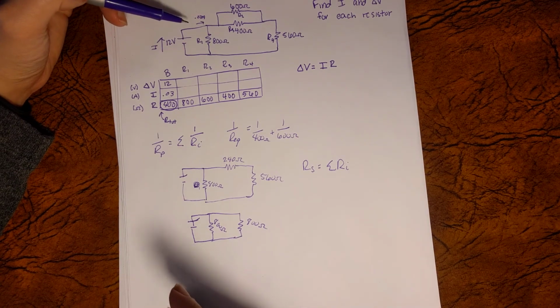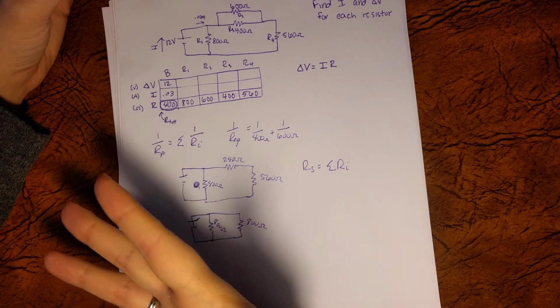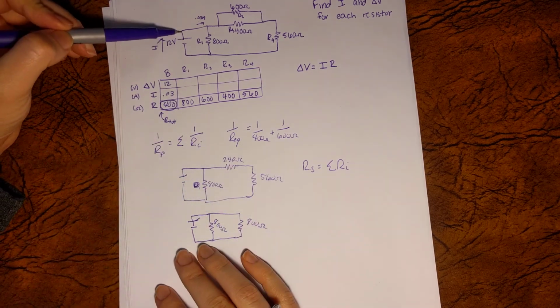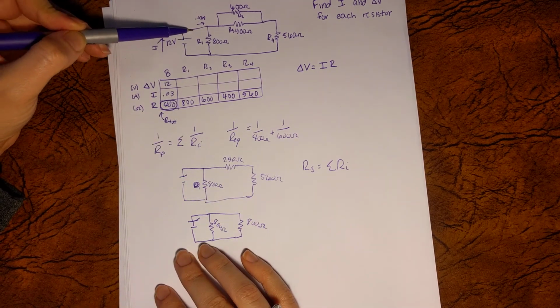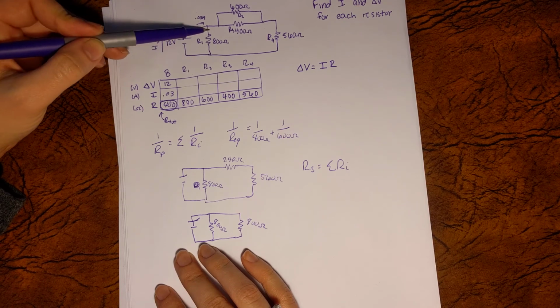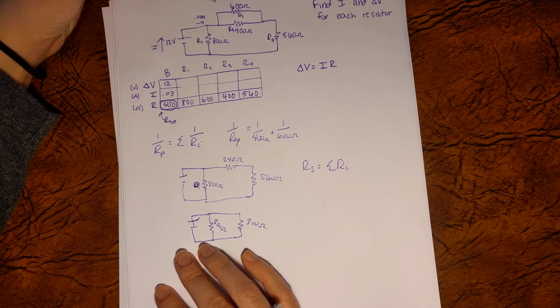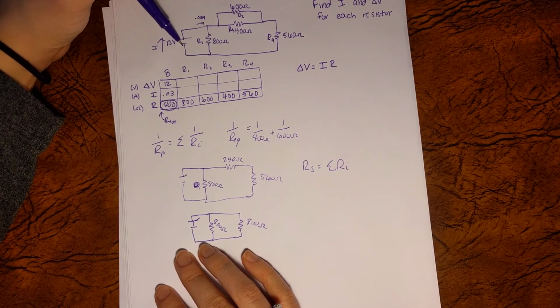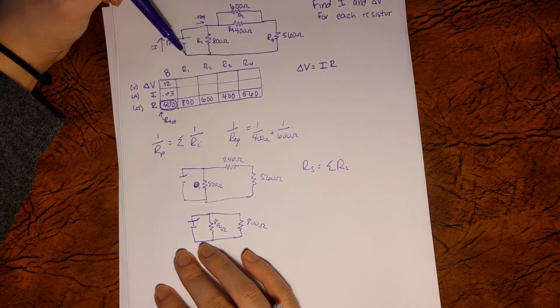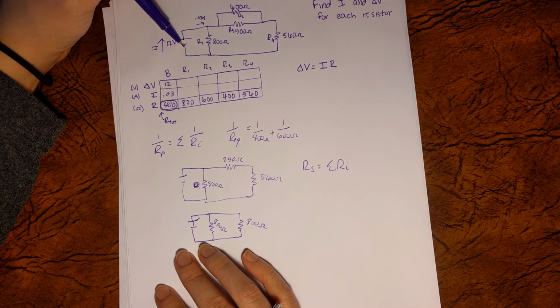Looking at the circuit here, let's apply Kirchhoff's loop law, because I see we have a very simple loop with one resistor, which is very nice. That's going to help us because we know that the voltage going around here has to drop to 0. It starts at 12, and has to end up at 0 if we complete the whole loop, right?